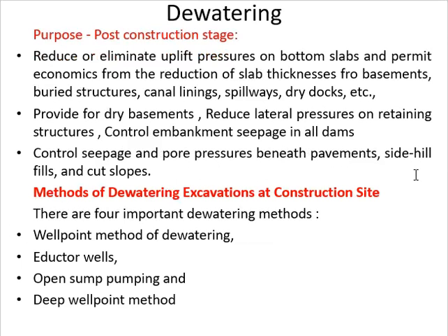And the dewatering after the construction reduces or eliminates the uplift pressures on bottom slabs and permits economies from the reduction of slab thickness of basements, buried structures, canal linings, spillways, dry docks, etc.